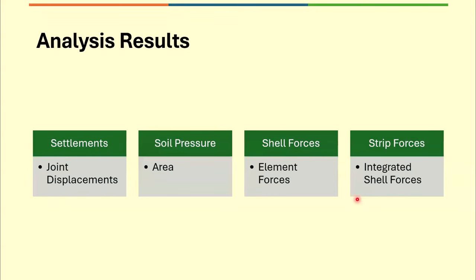Right. A few discussions on the analysis. I'm only giving the brief thing about the analysis process because we have discussed several analyses in the past. Basically, we are going to get the analysis results for those linear and nonlinear settlements, soil pressures, shell forces, element forces directly that can be read, or you can add strips that will give you an integrated shell force. Right? These are the things that are required in your foundation design.